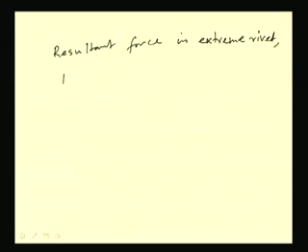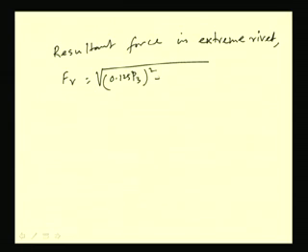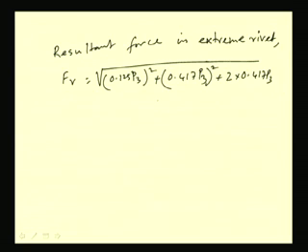that means we can write Fr will become Fa square, that means 0.125 P3 square, plus Fm square, that means 0.417 P3 square, plus 2 into 0.417 P3 into 0.125 P3 into cos 56.3. So, from this calculation finally we will get this as 0.5 P3.